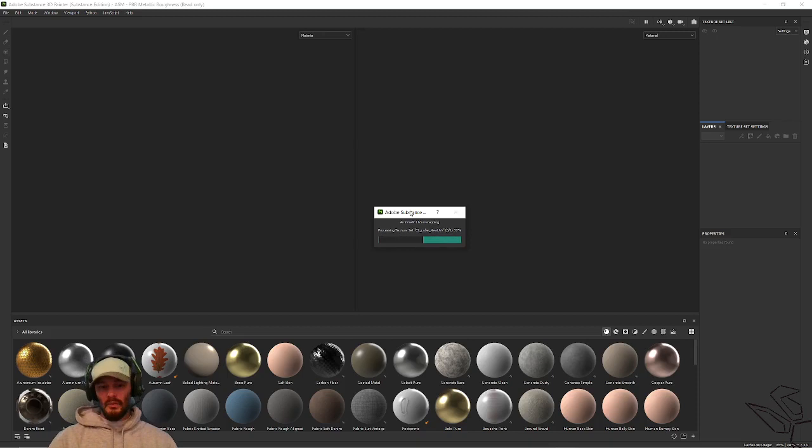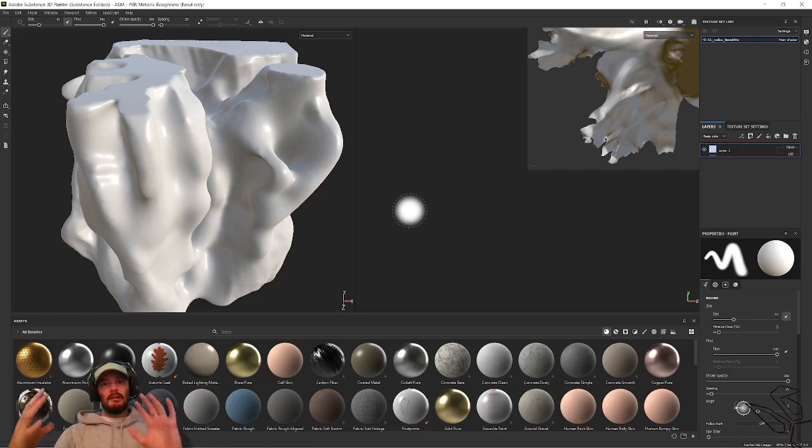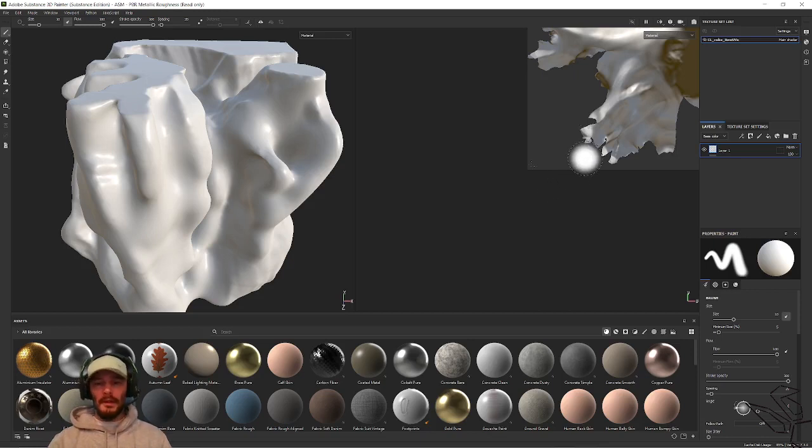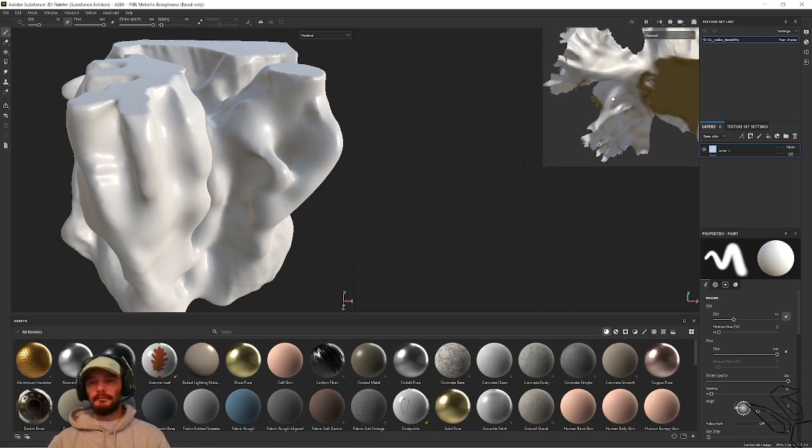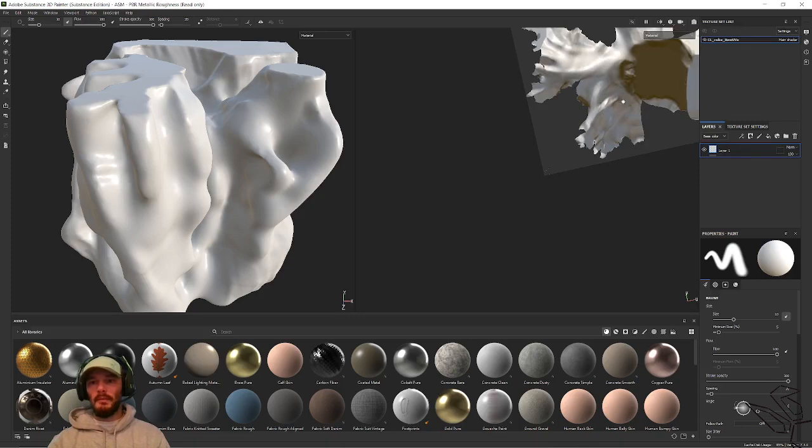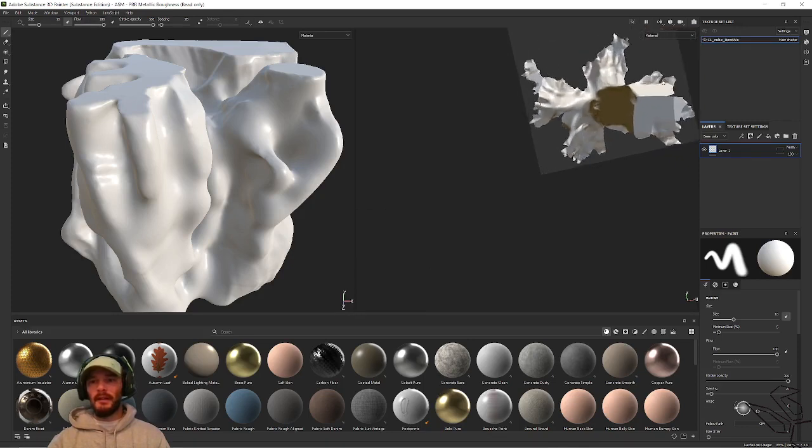So when you have an object in Chief Architect, like a table, that's a mesh, and there are different projections of that mesh. A table is pretty easy. It's six sides. If I were to say I want to apply a material based on a box, that's really simple to map, because it's going to apply a material and close it in from six different directions. Now, when you unwrap that, you come up with something like this over here. Let's see if I remember all the buttons. All the buttons are different from one program to the next, I'll tell you that.